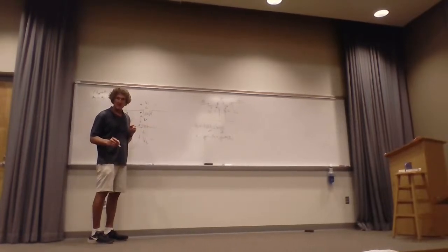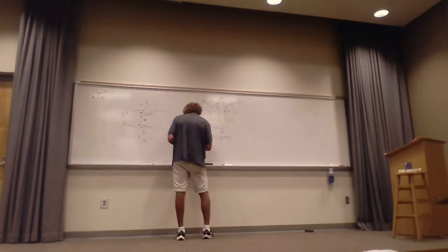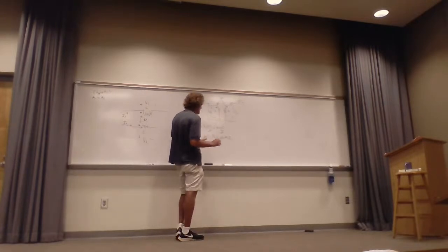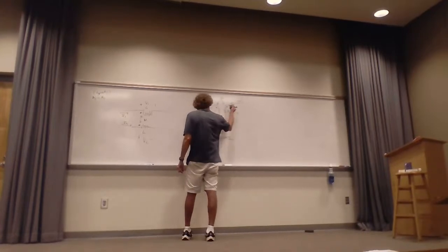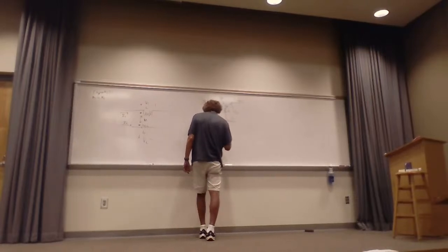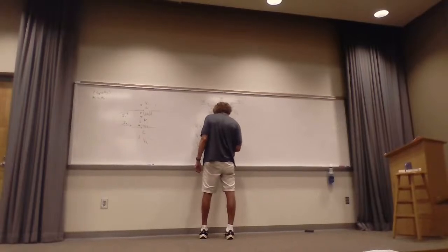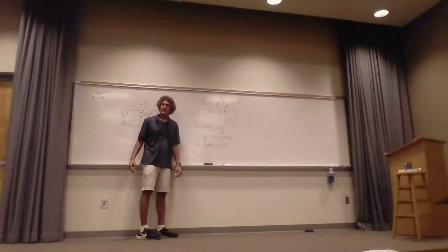Do you follow me? So the way I like to write this to keep everything consistent is I can say that V2, normally it would be L dI2/dt, the self, the EMF caused by the time derivative of the current into the inductance itself. But I'll just call it j omega, and here I'll use the mutual first, M times I1, plus j omega L times I2. Now the reason I did this is so I have I1 and I2 vertically on top of each other, and I can create a matrix if I want very easily. Follow me?